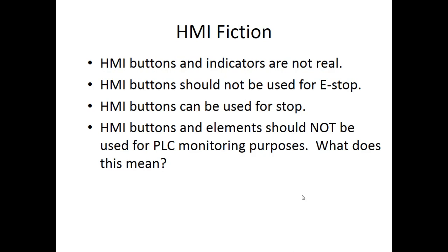And so if you're going to use the status of those buttons for more control, that could maybe get you in trouble. Okay, so they are used for indicating what's going on, but when we get into more advanced topics of monitoring devices and dual check safety and stuff like that, you'll see that HMI is good for indicating, not fully suitable for safety control.